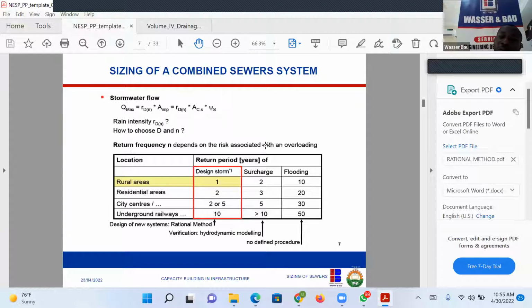And that risk is the risk of what will happen if this place is flooded. Like rural areas, we don't design for flooding in rural areas because if there is flood, it's farmland. Some crops will just die. Next season will start again. So there's no risk. I won't go and start spending 3 billion as against spending 1 billion to protect crops like maize and mango. So sometimes we say it's a political decision, but all of it is embedded in risk, and you, the designer, should know the level of risk associated with the design.